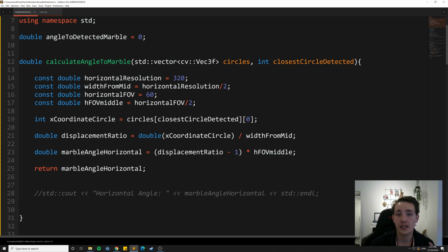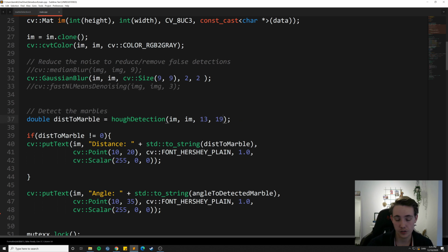This is so we can converge when we are trying to orient our robot towards the middle of the detected model. Then it will converge towards angle 0. And if there's a displacement in one of the directions, it will adjust for that displacement and try to go directly to the center of the model. So this is how we can do the actual calculations of the angle toward the model and also distances.